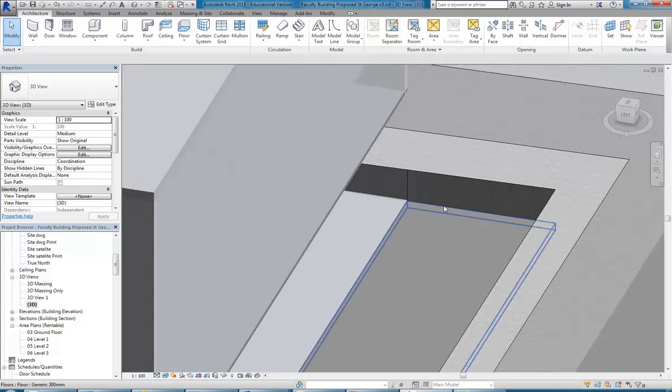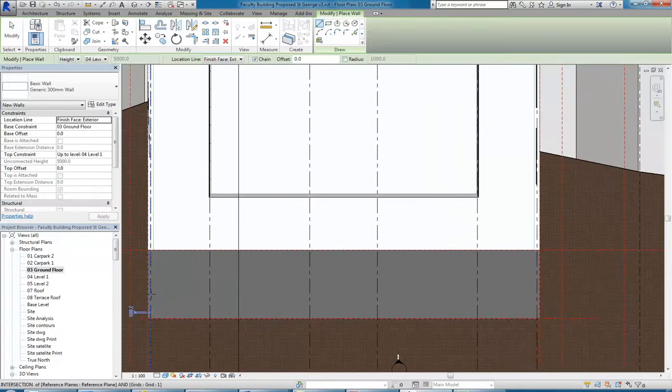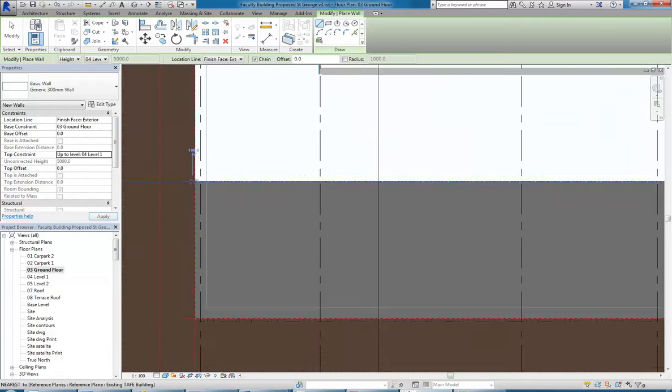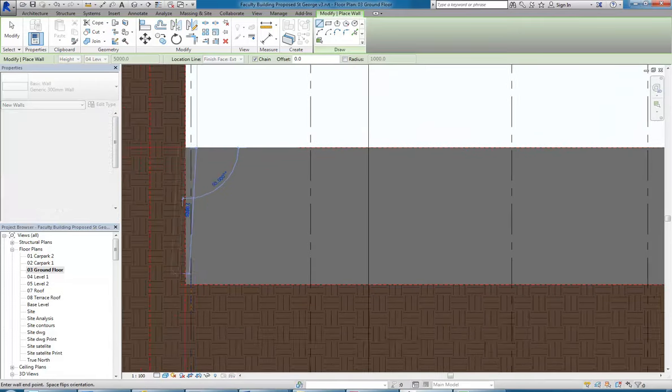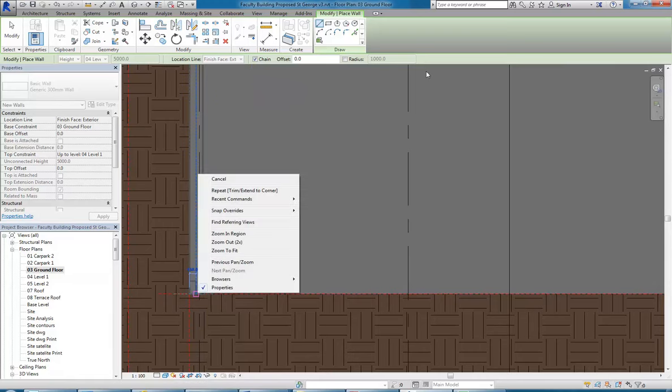And so in that case you can just do a regular wall. It's still a retaining wall, so structurally it's different to probably your normal exterior walls, but you don't have to worry about tanking. And so you can draw that just using the regular wall tool. That should be pretty straightforward. So I'm just going to draw some standard walls here, and I'm going to make the level 1. Doesn't really matter at the moment, so I'll have to adjust the height in a minute. I'm going to draw it anti-clockwise, but remember you can always press space as you draw any wall to flip it to go the other way, so you don't always have to draw clockwise.